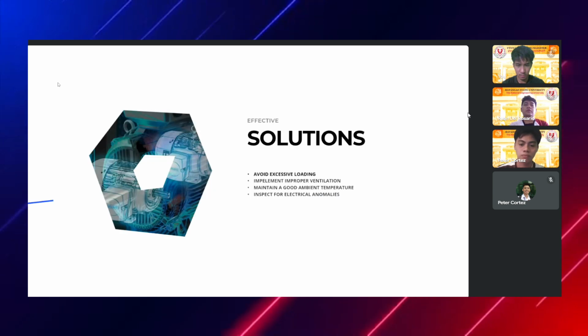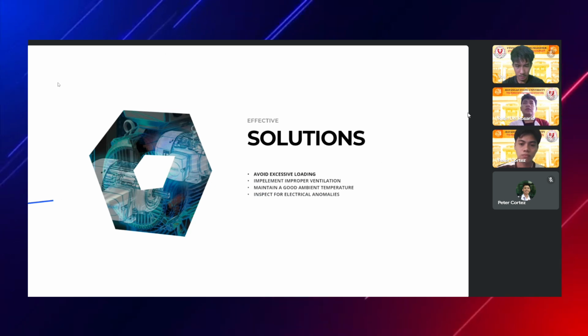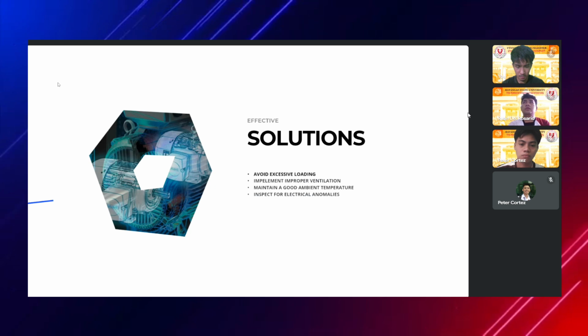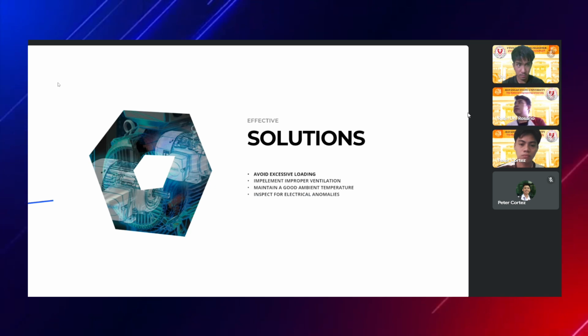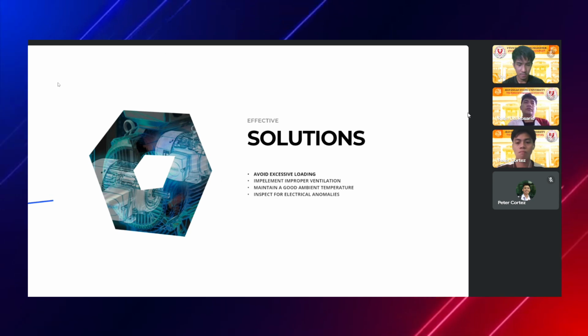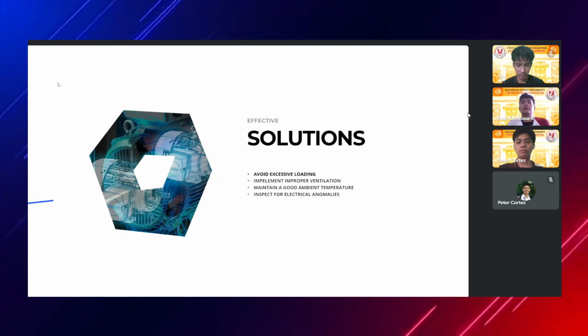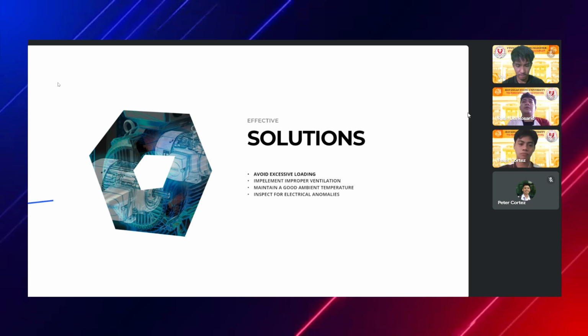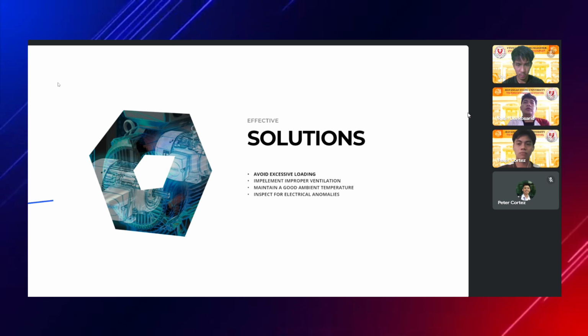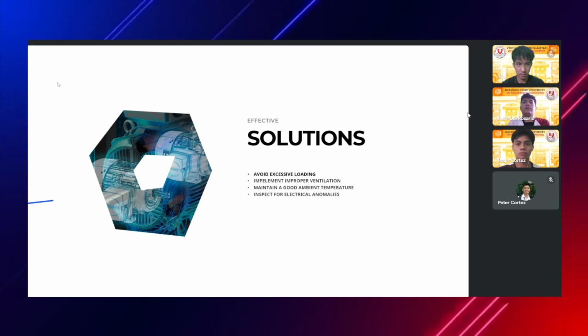So this is the effective solutions. First is to avoid excessive loading. Second is to implement proper ventilation. Third is to maintain a good ambient temperature and lastly, inspect for electrical anomalies.